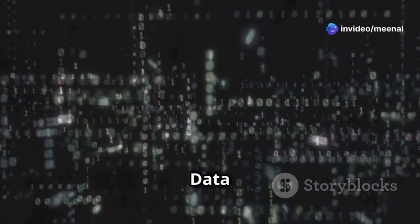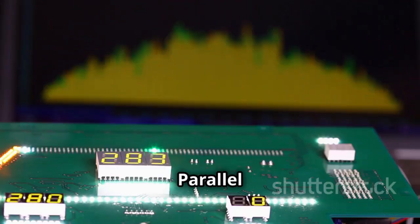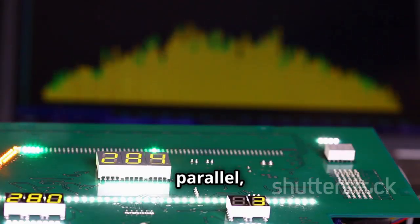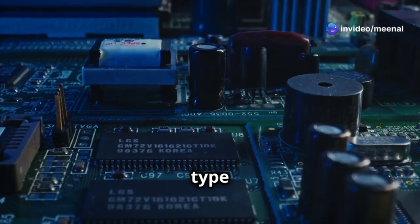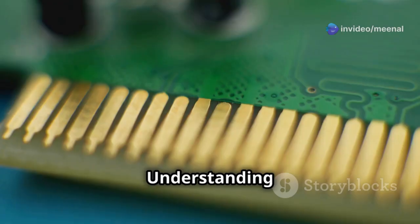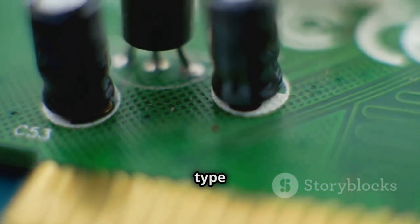Parallel in, serial out, PISO. Data is loaded in parallel but exits the register serially. Parallel in, parallel out, PIPO. Data is loaded and retrieved in parallel, allowing for simultaneous input and output. Each type of shift register serves specific purposes in digital circuits. Understanding their unique characteristics is crucial for selecting the appropriate type for a particular application.